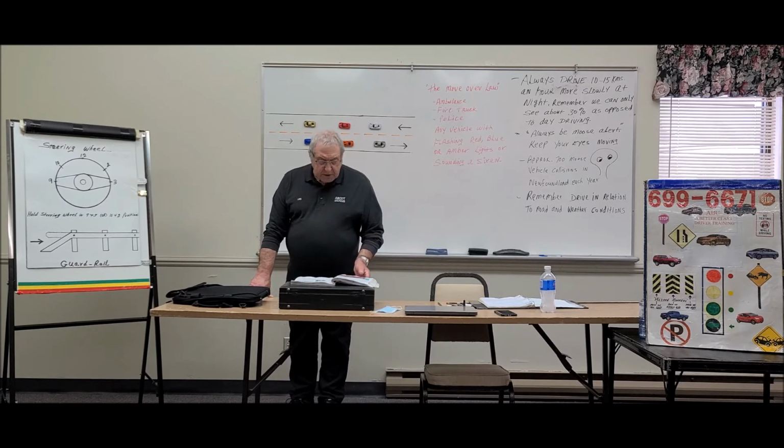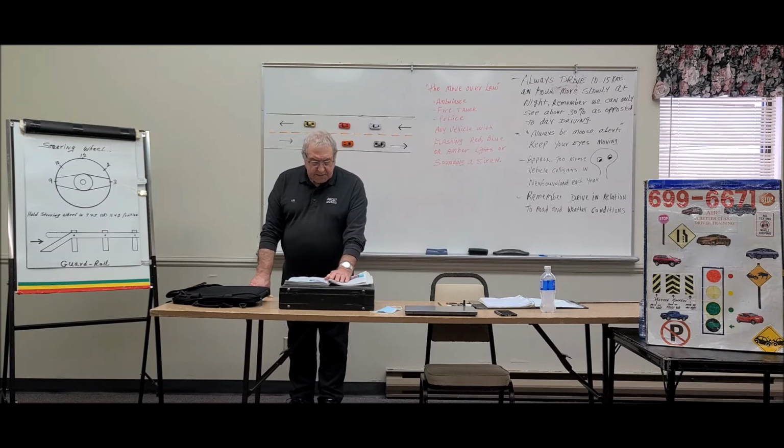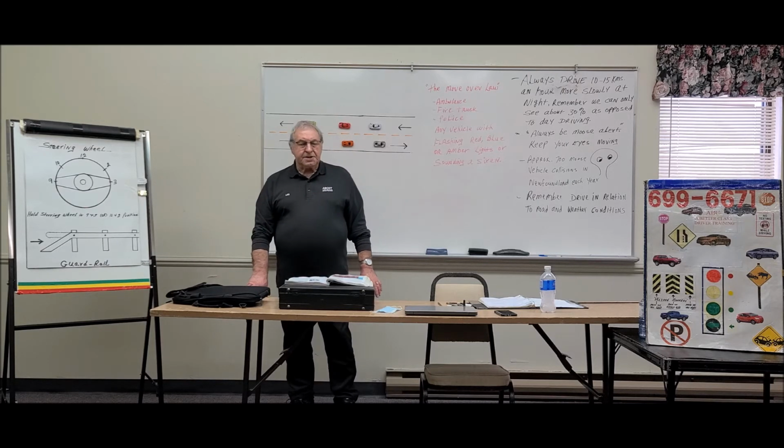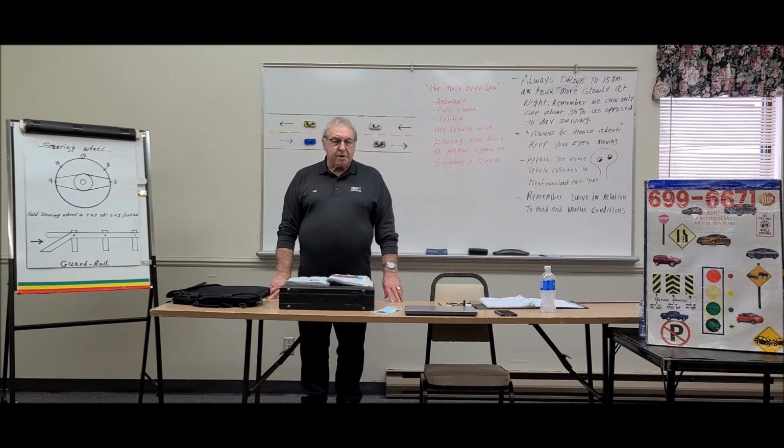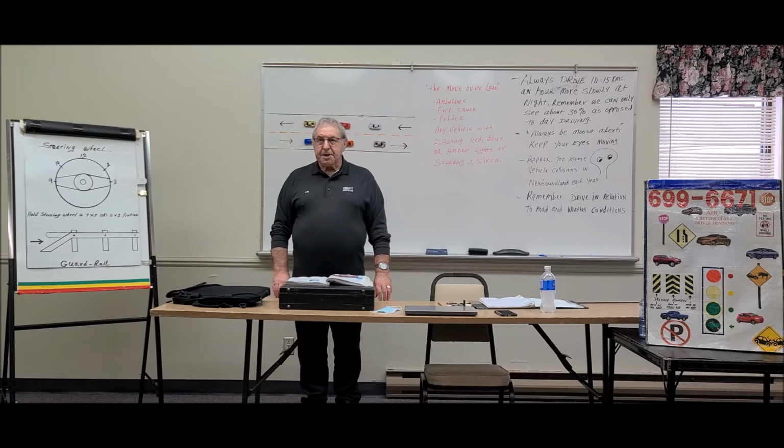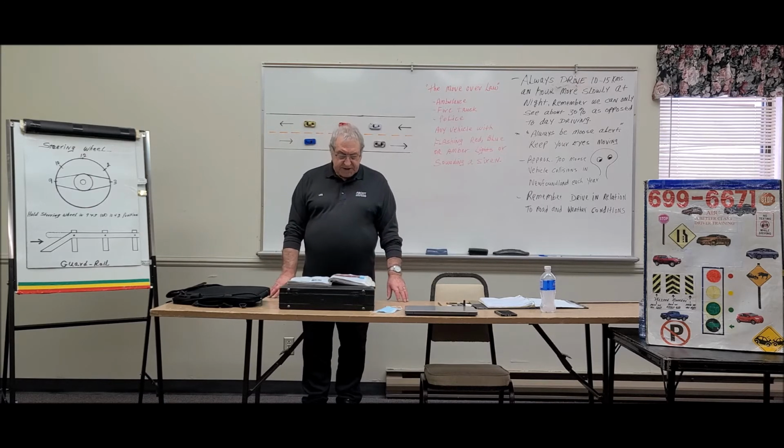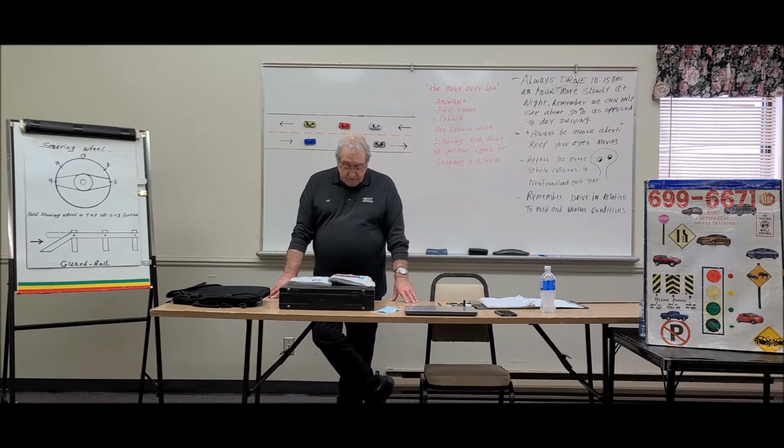And that's not so much with our gas vehicles, but particularly with diesel engines, lots of times you have to turn on the key and there's a light in your dash called a glow plug light, and you have to wait maybe 30-40 seconds so that the glow plug in your engine will warm the cylinders. Then of course you turn the key over to the start position and you hear your engine chugging over or cranking over and the engine will start. That's typical of diesel engines, for sure.